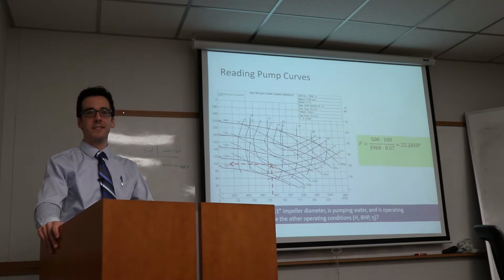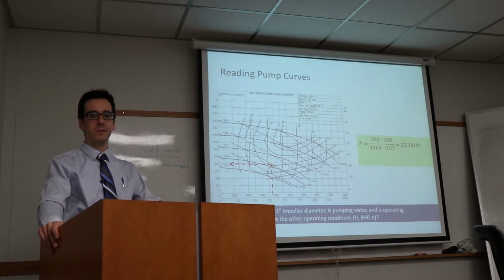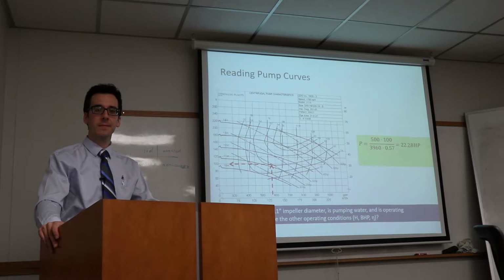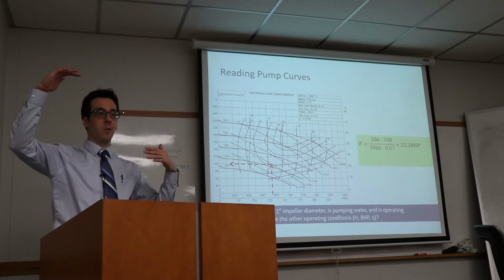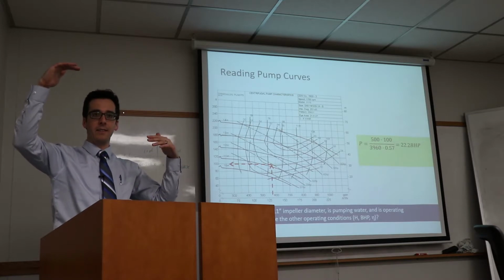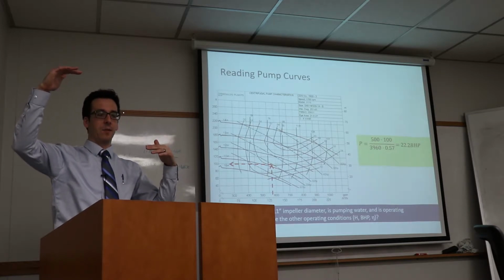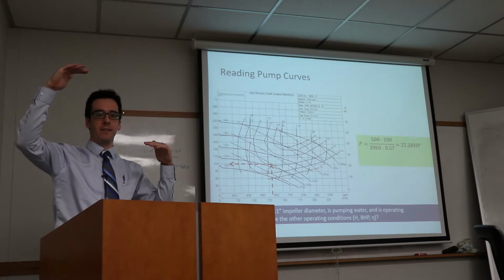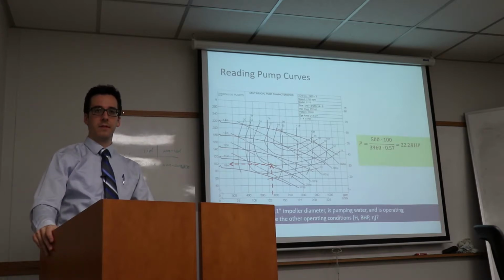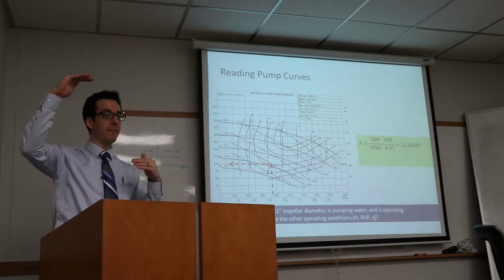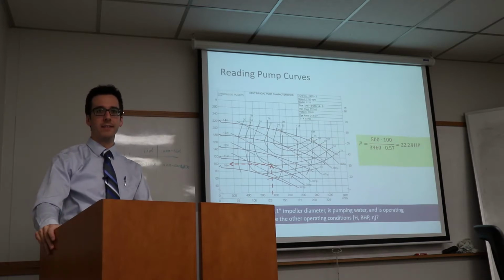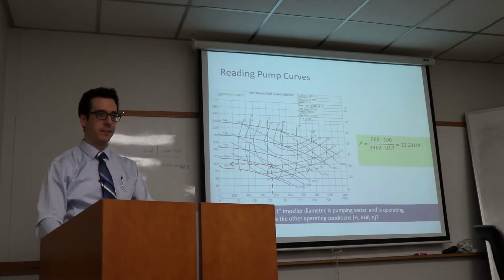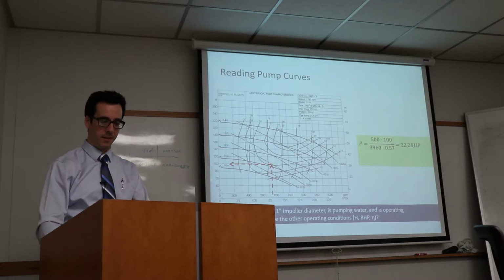Well, okay, so back to that example where you have 2 tanks. Are the 2 tanks at different pressures then? So the 2 tanks are at different elevations, and the water's not pressurized. It's just floating in there. It's just breathing. And so we're trying to move water from one tank to another. So in that example, it's just to overcome the head loss. Yeah, first of all, the static head, the elevation difference, plus any head losses that occur during conveyance. Okay. Yes. And we'll have some practice doing this in just a few minutes.